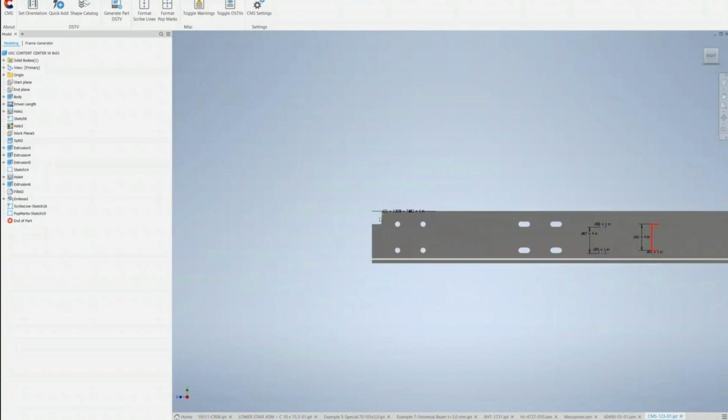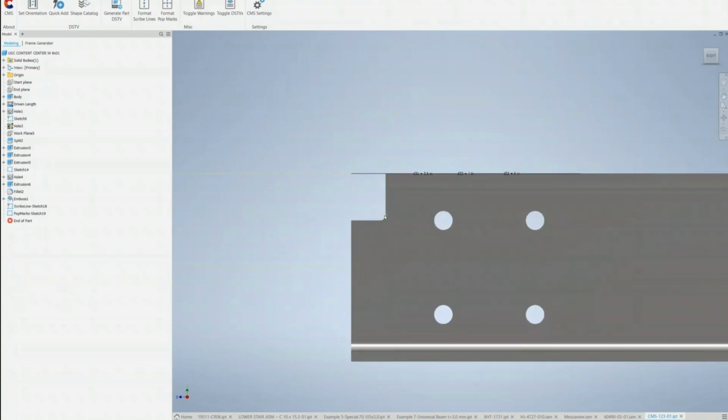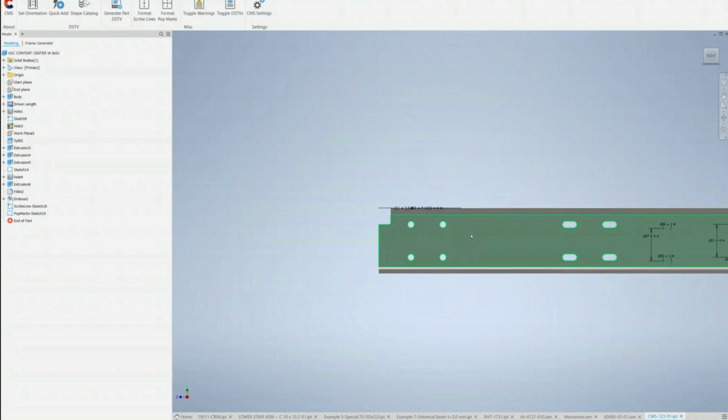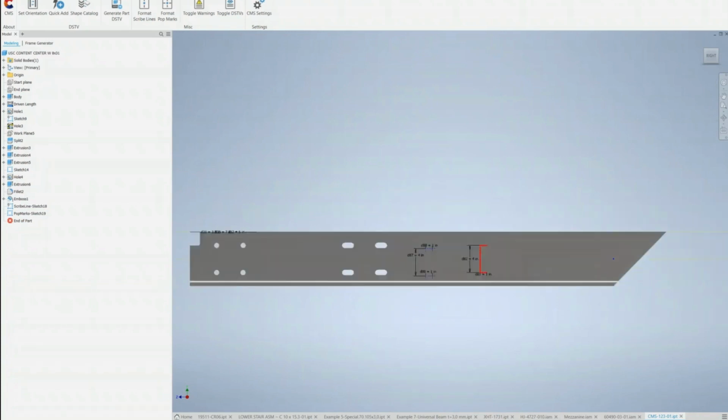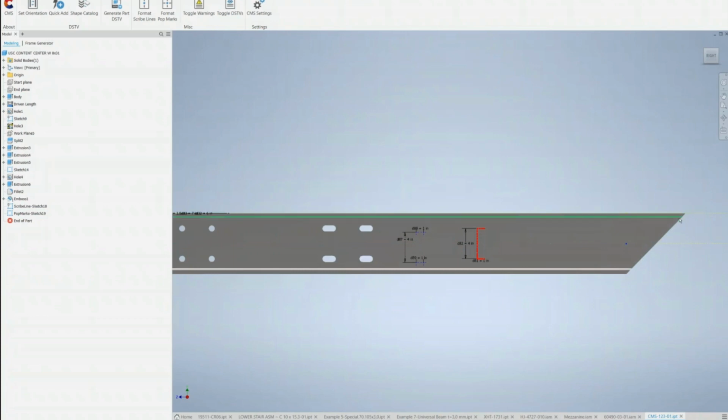As you see again, I have a cope fillet over here, so I have a radius involved. I have some drills and slots, and at the same time I have a miter. Due to that miter, I will be expecting a top and bottom flange, and on the top and bottom flange, I'll be expecting 2 bevels. So the software should also get those bevel descriptions.